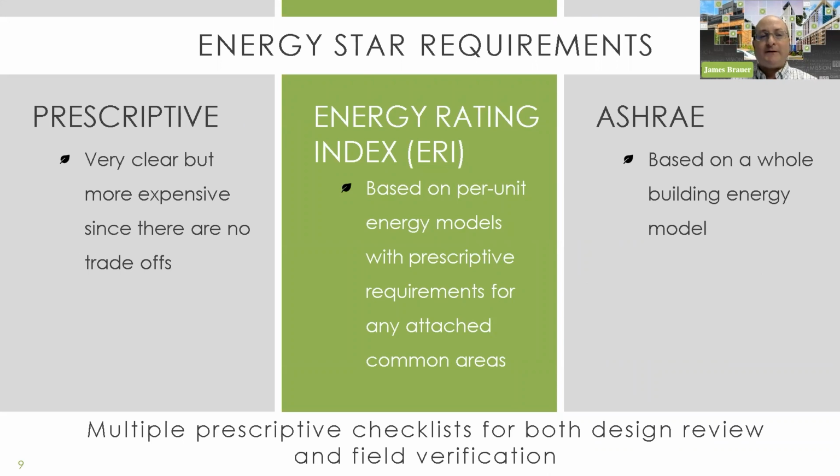All right, so with Energy Star, you do have three options for the pathway to choose. You can do a prescriptive pathway. It is very clear, there's no energy model needed, but it can at times be more expensive since there are no trade-offs with efficiency when you do an energy model. Since it's an all or nothing checklist, you must abide or exceed all measures, and that's where some additional expense can be incurred.